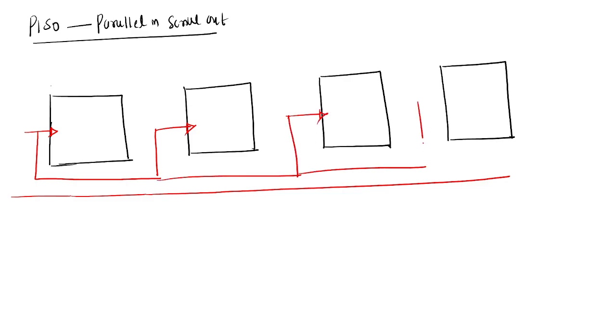So a common clock is given to all the flip flops. And next, the inputs and outputs are D3, Q3, D2, Q2, D1, Q1, D naught, Q naught. Here again you are using 2 cross 1 muxes. In the first one, one input is D3.